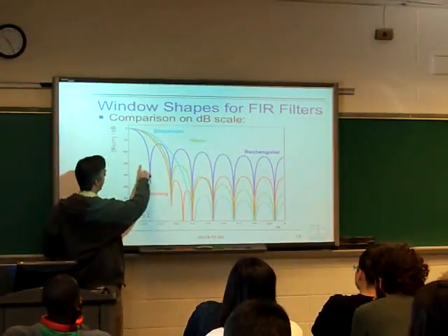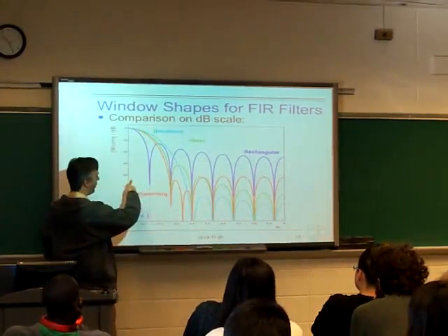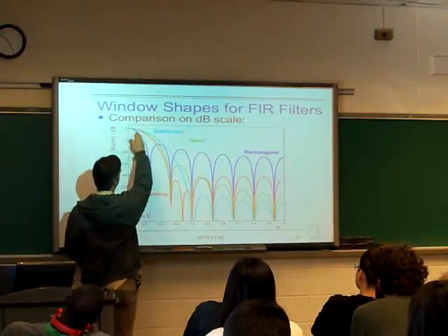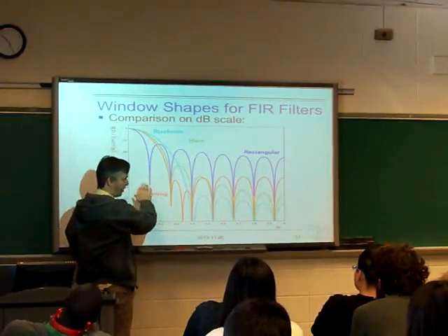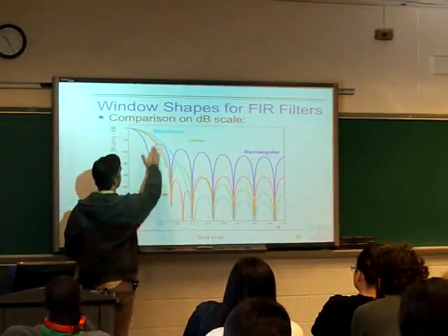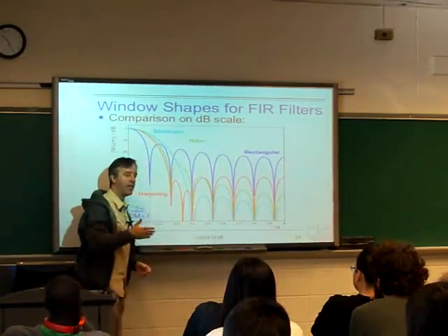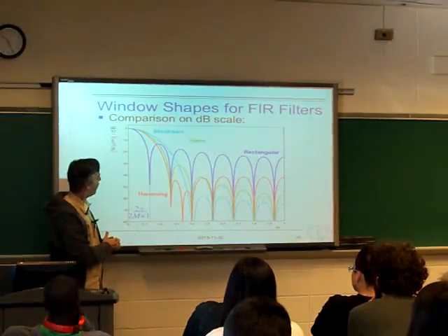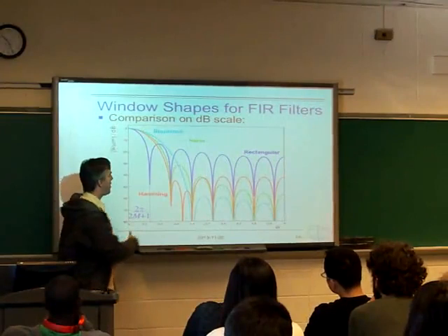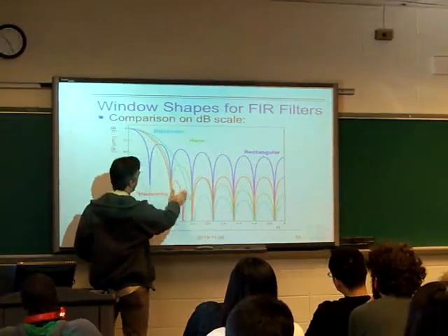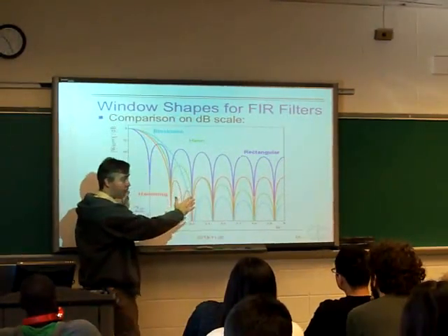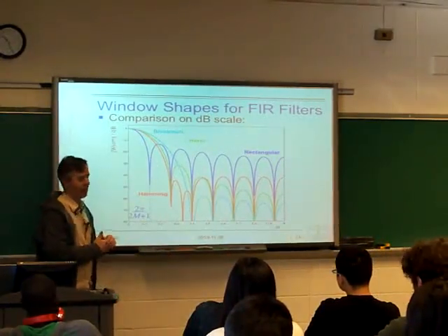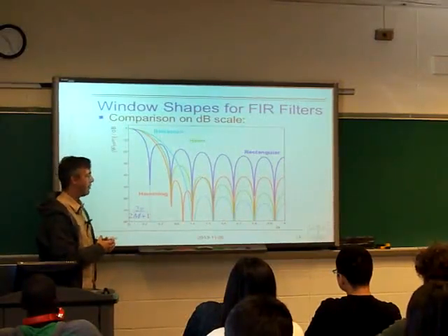Because with the rectangular window, if you look at the frequency response, you've got the main lobe, you've gone down to a low value, but then suddenly it reappears and keeps reappearing, and so you get these sort of echoes of the frequency edge showing up, which are quite disturbing. And sometimes it's nicer just to have something that's fairly smooth, maybe fairly soft, with a broad transition band, but once you've gone through the transition band, you're not going to see any additional features showing up.